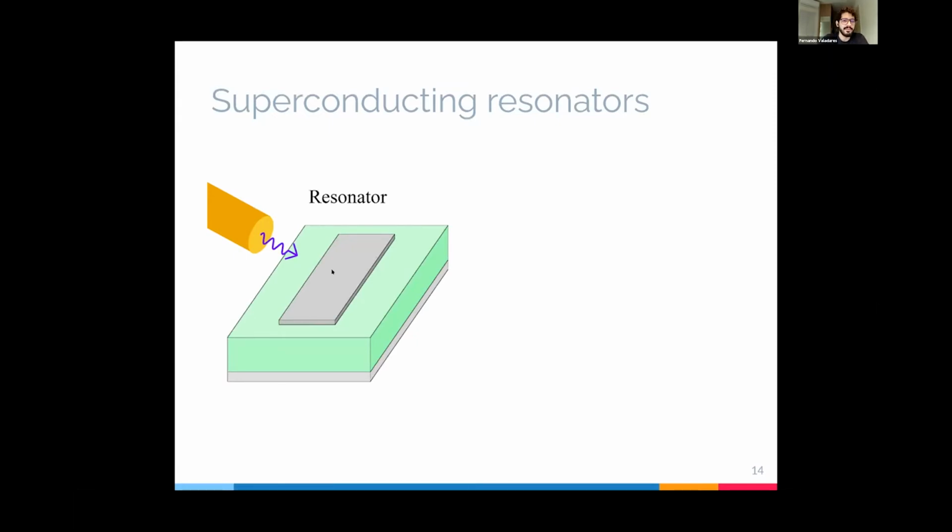I want you to think of the resonator as the electromagnetic analog of a guitar string, a mechanical string. Because think of the guitar string, it is held at both its ends. So if you stimulate a perturbation on it, if you hit it, this perturbation will flow to both sides and hit back and forth at these two ends. And this vibration will add up to a fixed frequency of oscillation. That's how you can tune your string by changing its properties. You can change this frequency.